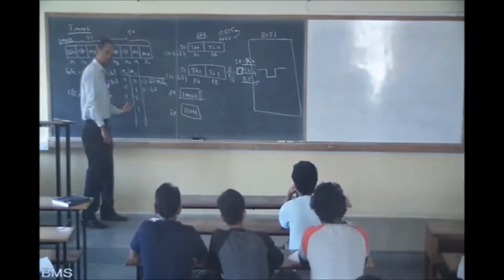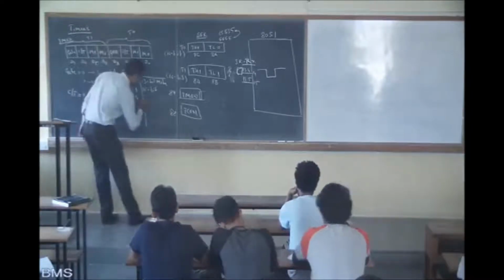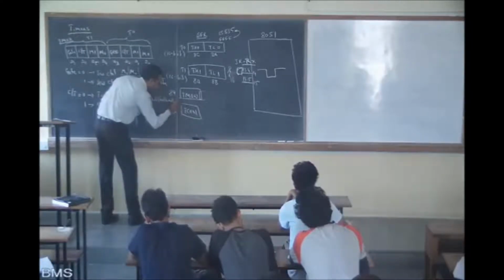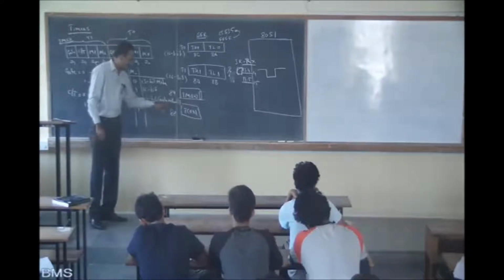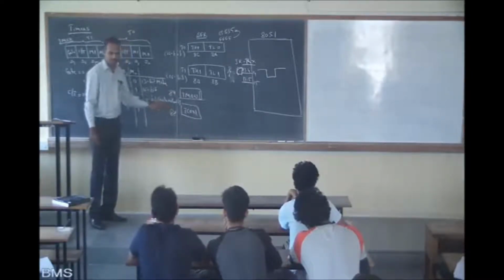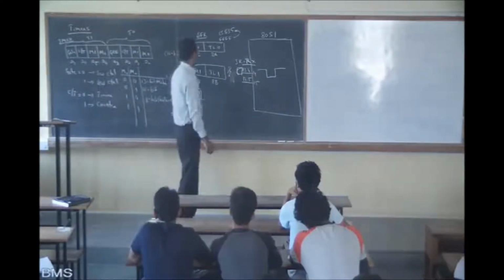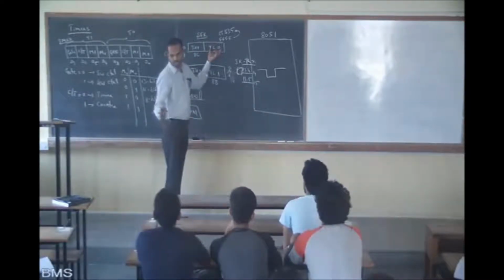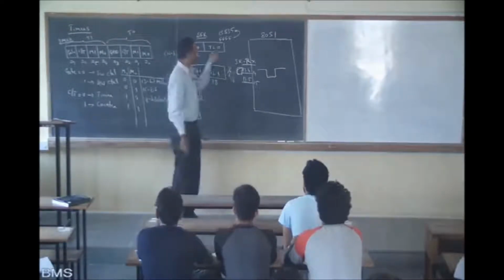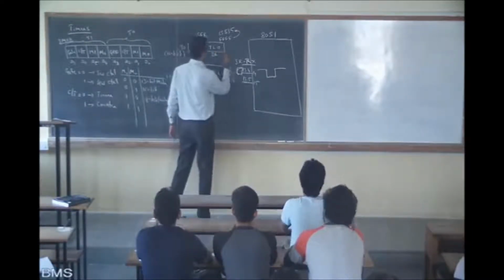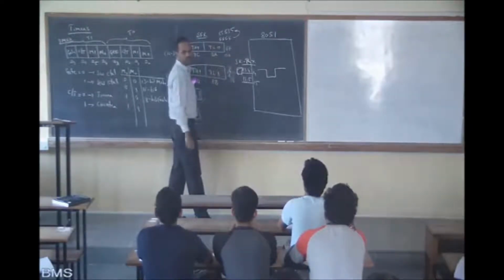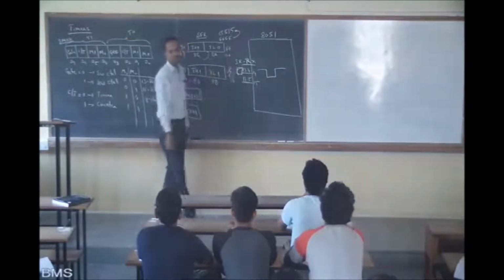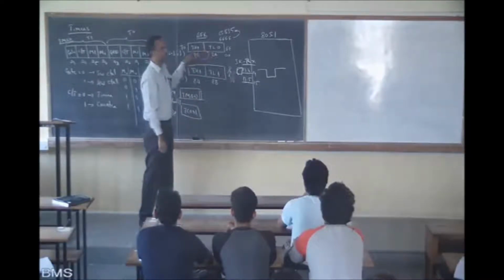Next, mode 2. Mode 2 is the 8-bit auto reload mode. What happens in this? Now listen. In TL0 we put some value. It is 8-bit mode, which means only this register is acting now. If you put 00 here, it will count up to the maximum FF. Again, when it finishes FF, it takes the value from TH0. Whatever value you want to give, you put it in here.